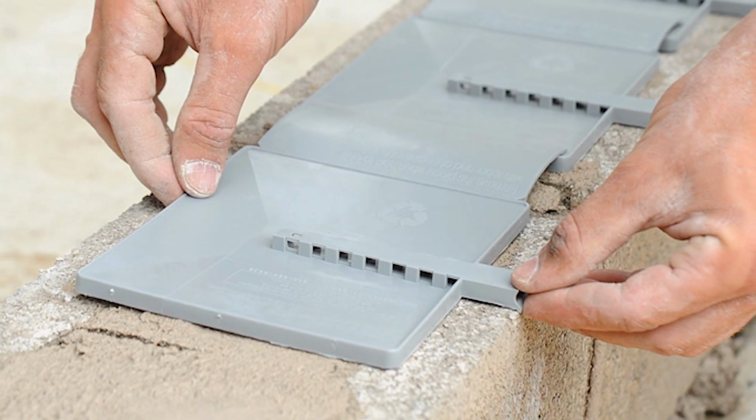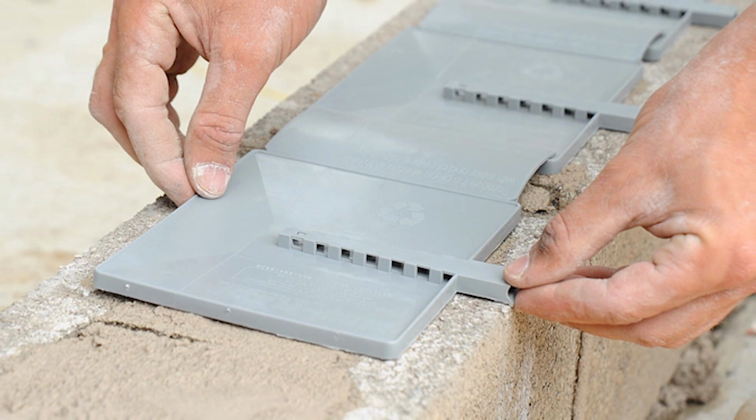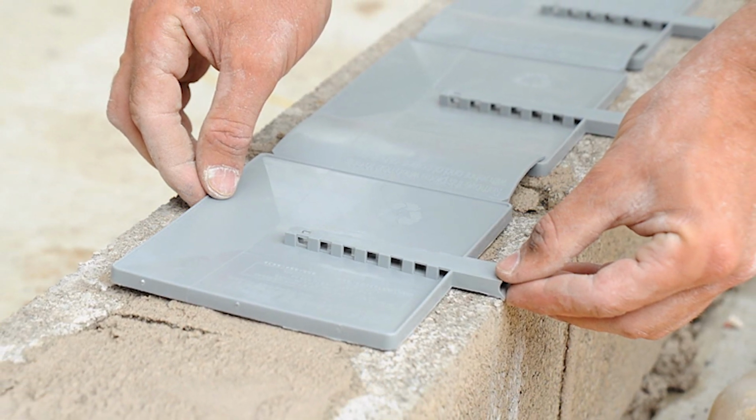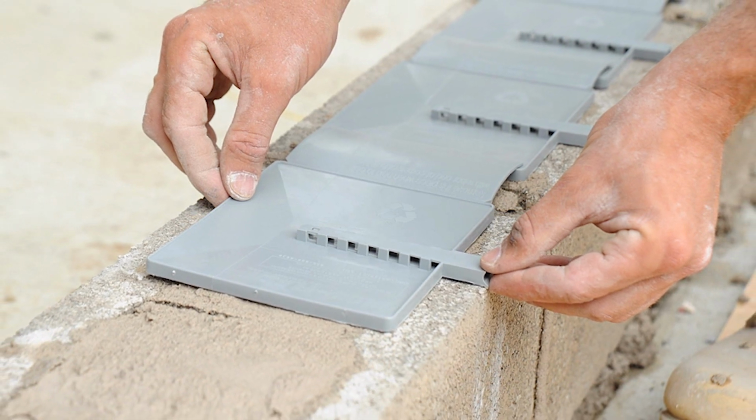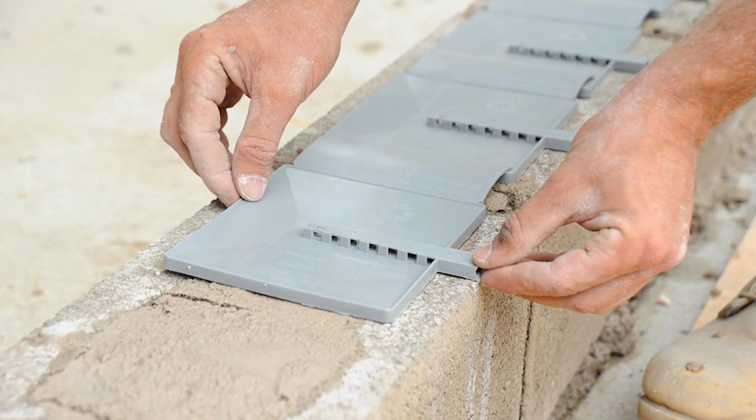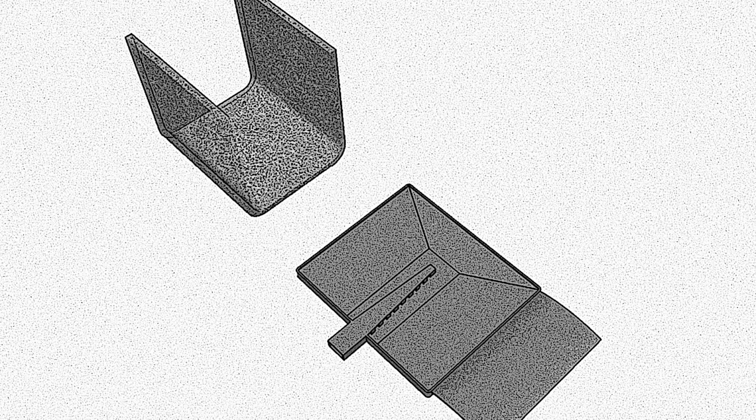In addition to metal or flexible flashing systems, pan-type flashing systems are available for single-width drainage walls that direct water away from the inside face of the wall to weep holes without compromising the bond and mortar joints in the face shells. Typically, these systems consist of a drainage pan that incorporates a weep hole and a mortar control device to ensure the system remains unclogged.